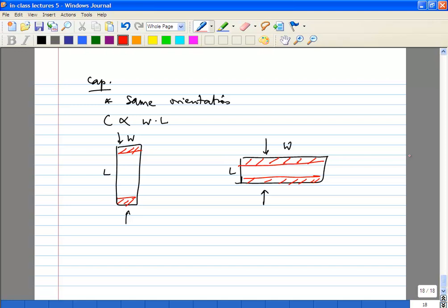What you can do is kill a perfectly good design by doing something very bad with the capacitors. I assume you all know about this. Let's just take some inductance in the supply, and let's say your input is a clock. What is your output going to look like? First of all, this inverter is going to draw switching current. Every time it switches, it's going to draw a pulse of current. The inductor doesn't like changes in current, you're going to get L dI/dt drops.